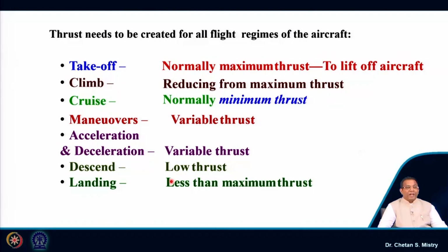So, just realize a very important criterion. When we are designing our engine, our maximum thrust is at takeoff. So, the engine needs to be designed at the maximum thrust condition. If I am unable to take off my aircraft, then that engine is of no use. So, we need to be very careful. All engines are designed at the maximum thrust condition, my takeoff condition, and this takeoff condition is taken as the design condition.